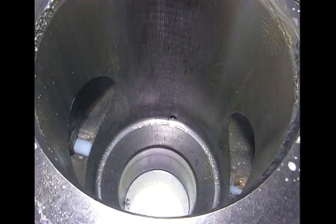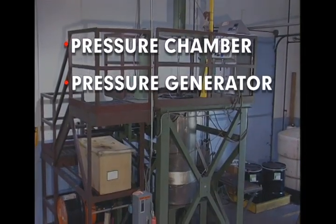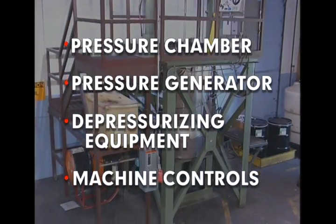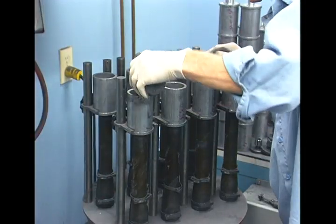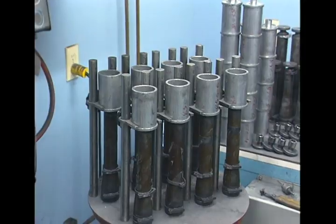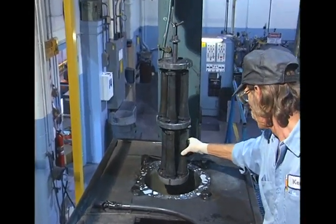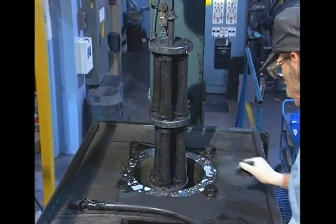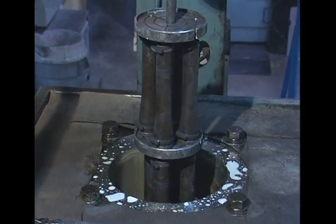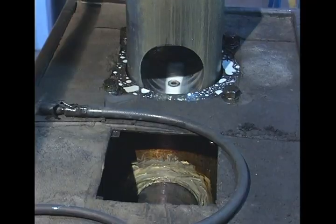The press for cold isostatic pressing includes a pressure chamber, pressure generator, depressurizing equipment, and machine controls. The powder is placed in a flexible, pre-shaped elastomeric mold, also called a bag, and consolidated by high-pressure water or oil. Pressures range from 10,000 to 70,000 psi, depending on the powder being processed. Dwell time at full pressure is a few minutes.